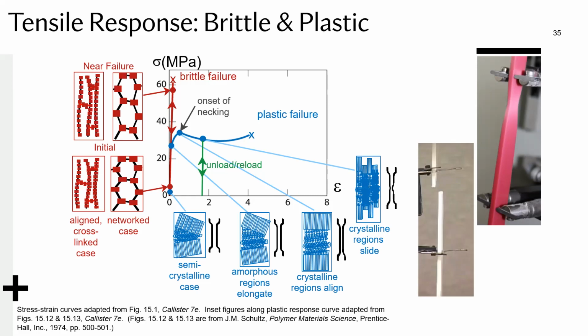That's why it can withstand these high elongations, but not higher stress. You can see that the stress level plateaus, and it doesn't go beyond that point. That's really the strength of this material. Beyond that point, it's just sliding, slipping and elongating. So that's why you have some rather special behavior in these semi-crystalline polymers.